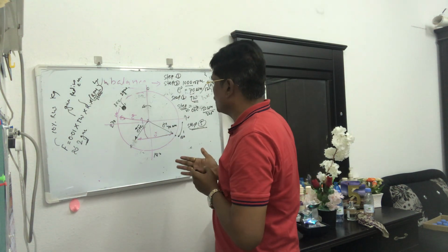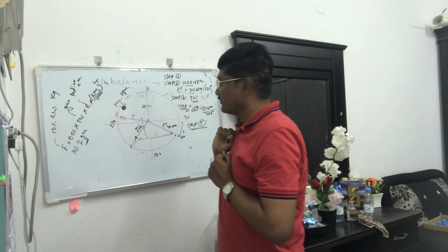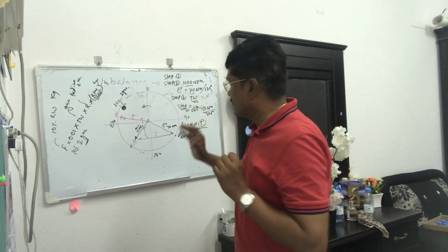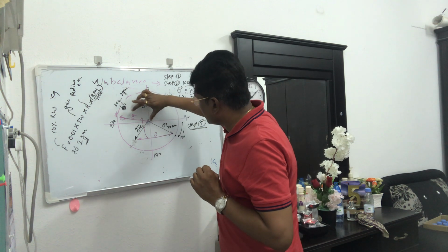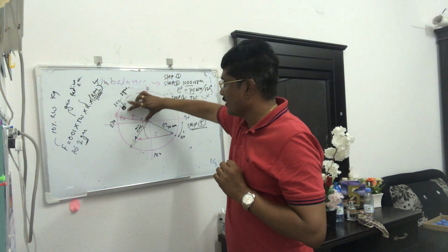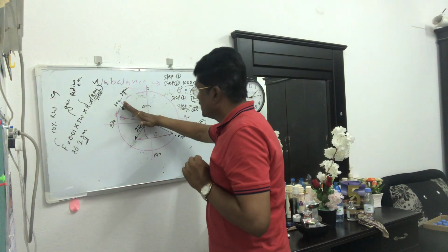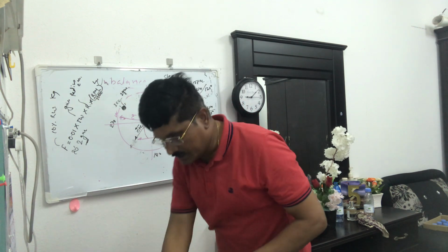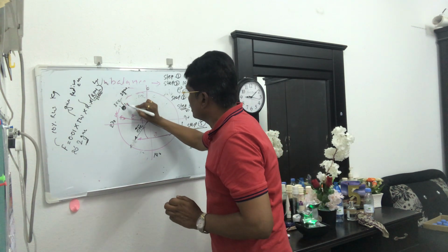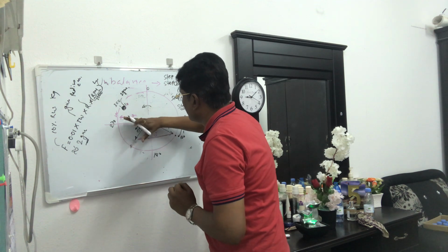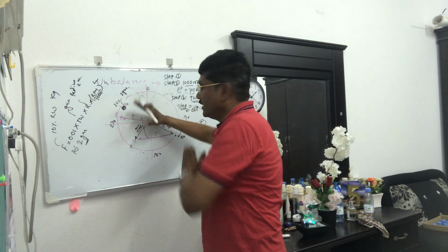So what do we have to do now? We have to remove this weight and add it in such a way that the effect becomes exactly opposite to this O vector. For that we have to shift it a little bit. If I shift this weight a little, suppose 10 degrees, then the effect will move away 10 degrees.